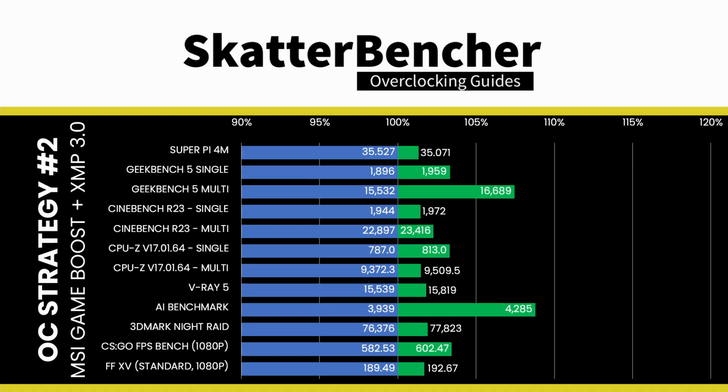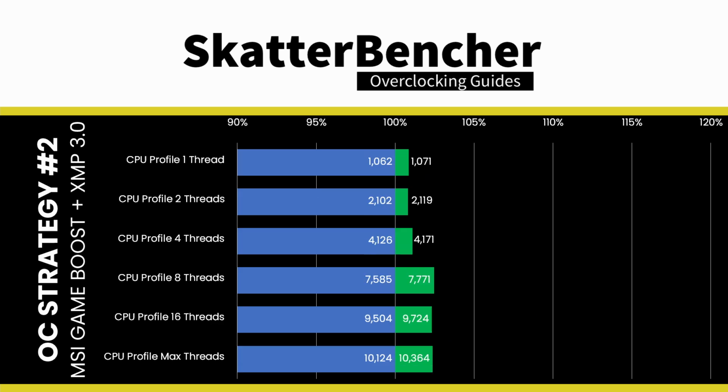We reran the benchmarks and check the performance increase compared to the default operation. The performance increase after a +1 ratio bump is not spectacular, but we do see some solid gains in multi-threaded benchmarks in particular. The largest increase is +8.78% in AI benchmark. Despite the use of an AVX negative ratio offset, we don't see any major implications on the benchmark result.